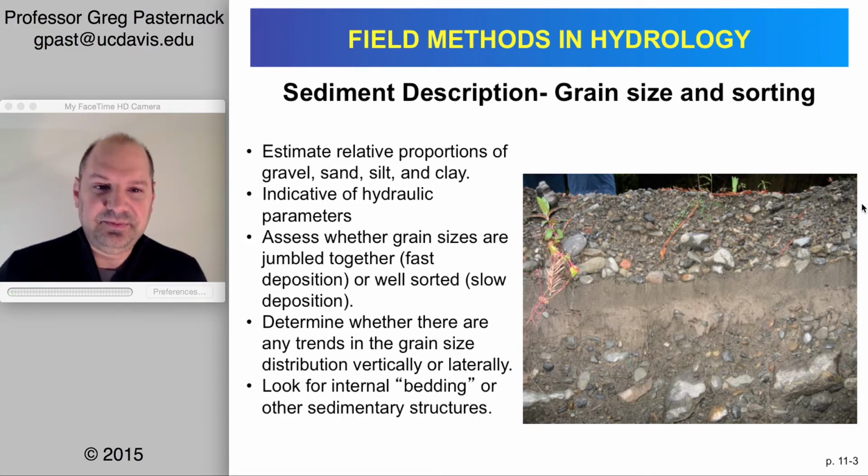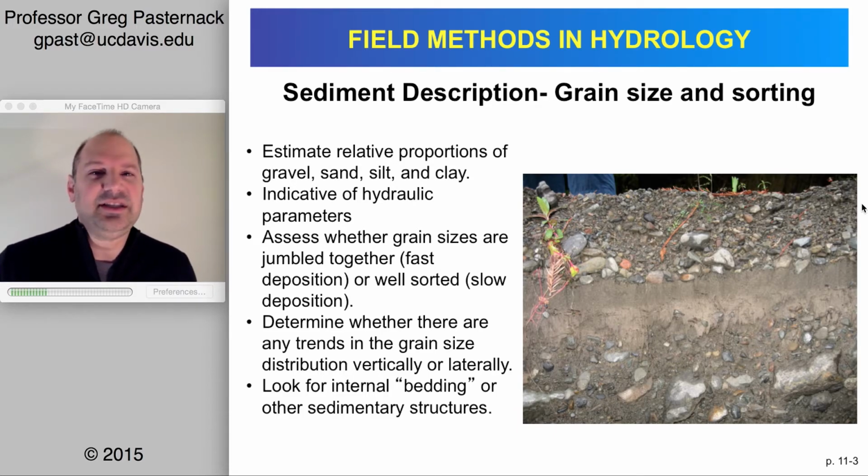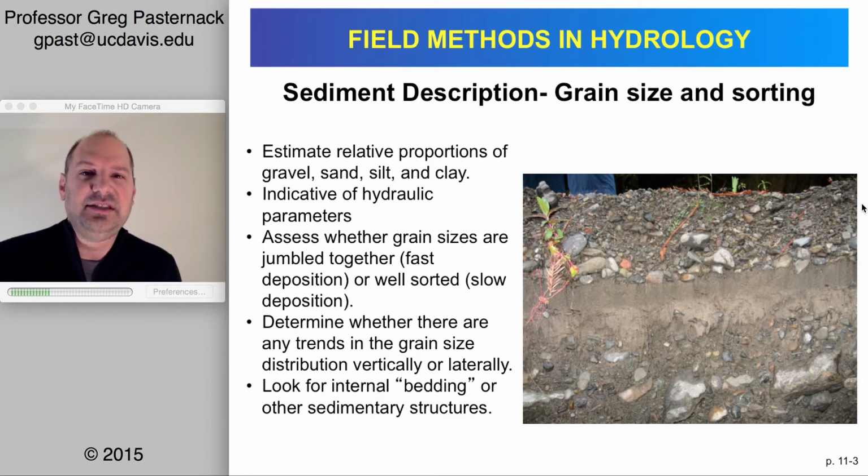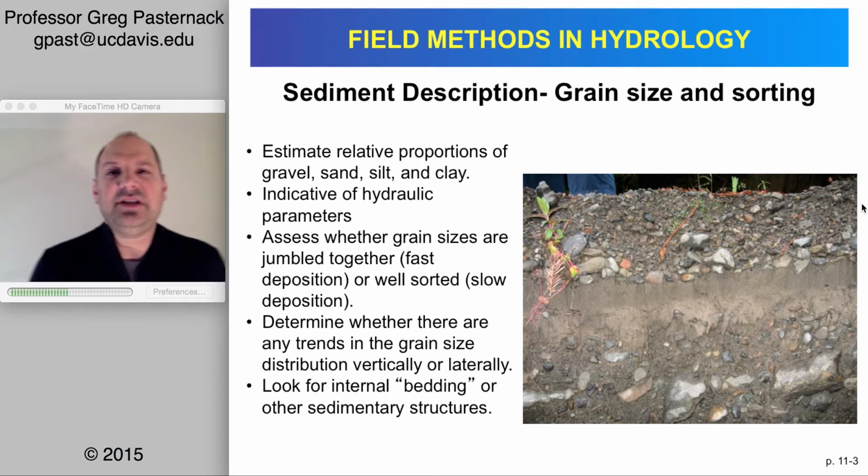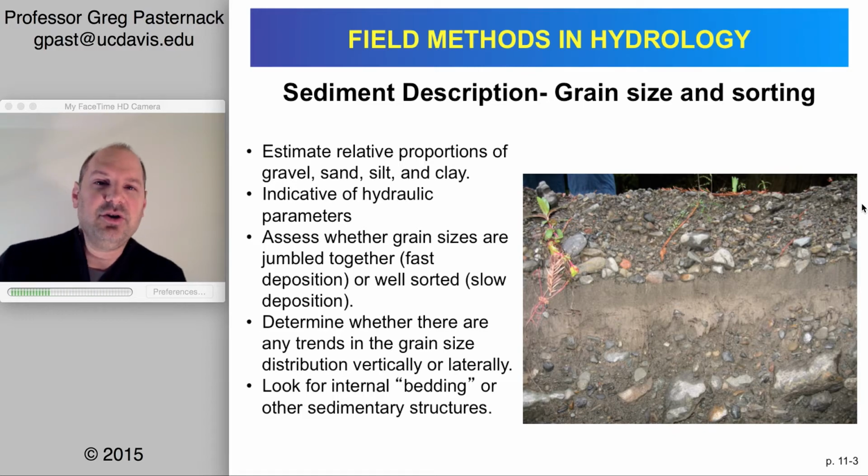When we talk about grain sizes, we want to know what is the size of individual grains, what is the size of the bulk medium itself, and we can think of those sizes in some very simplified groupings of sizes, which I'll show you in a moment, but typically we think of that as gravel, sand, silt, and clay. And the main reason that we focus on grain size is it tells us a lot about the ability of water to move through that material or over it.